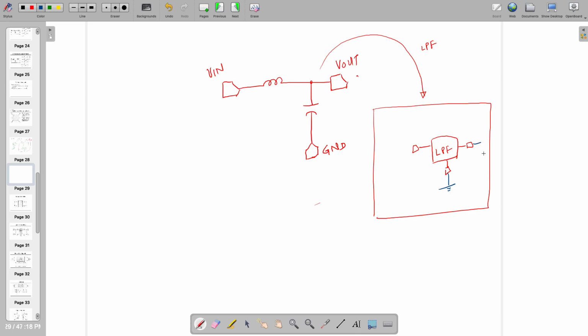Here I'm going to connect output, where it's asking for some load value, and at the input side you may have a function generator. So at this port you may have 50 ohm. This is from outside. So this is called a hierarchical test setup, where you are not going into the circuit.